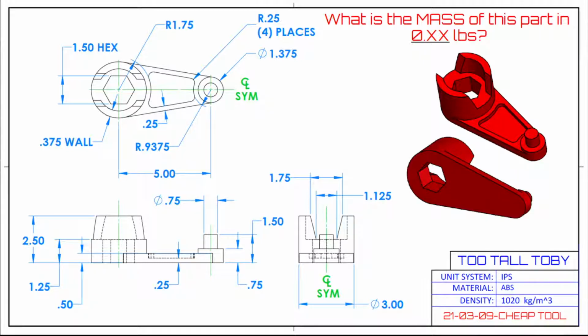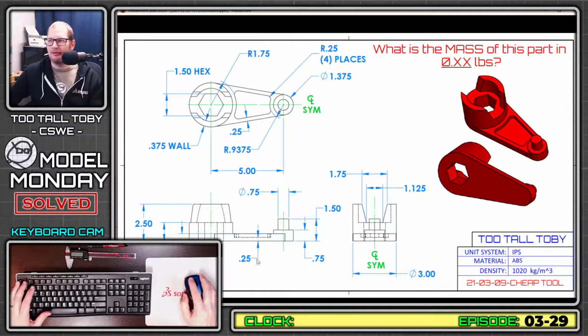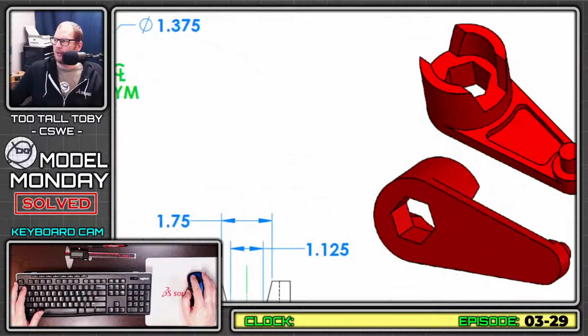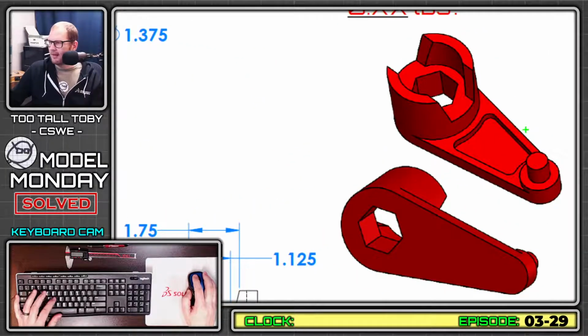If I take the diameter of that lower circle, which is 3, if I divide that in half to get to 1.5 and then I add 0.25, does that get me to radius 1.75? Maybe I could save some time and offset all those faces at the same time. I don't know, right? Let's get into it here and find out. But these would be all things that I'd be thinking about, and then it would come time to come up with my game plan. And for this one, my game plan is going to be create this all-in-one shape.